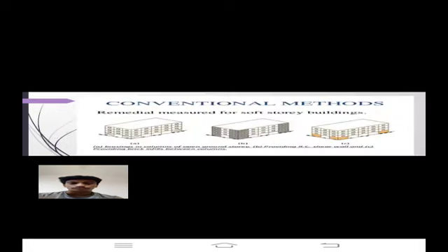There are some popular earthquake resistant techniques, which are conventional methods: shear walls, bracing, seismic dampers, isolation, bands, lightweight material. First, conventional methods. The concept is to strengthen the building, to have stiffness and inelastic deformation capacity. Some of the general design concepts: follow current earthquake standards and codes, provide a strong foundation, use best quality materials, avoid irregular shape structure and framing system, and maintain integrity by providing seismic bands.